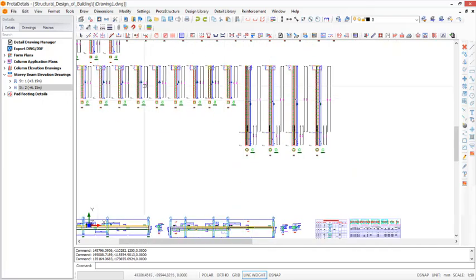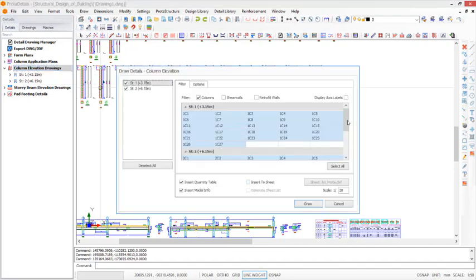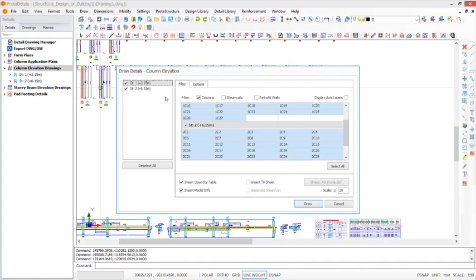All right, so for you to do that, get over to the column provisions. In these provisions, you can select this, right click on this, and you can see draw columns elevations, and then draw columns elevations one by one. So you don't use these provisions. You can also come to this column elevations drawings, right click and click on draw columns elevations schedule, draw columns elevations, click these first options,